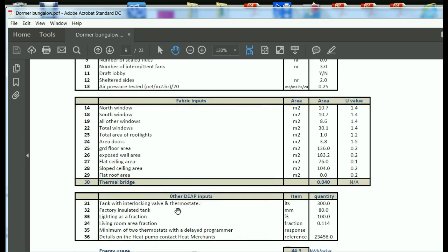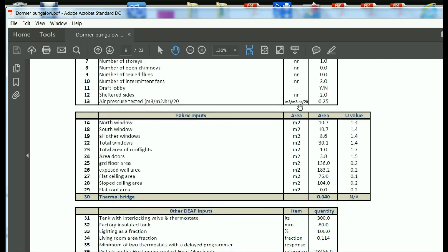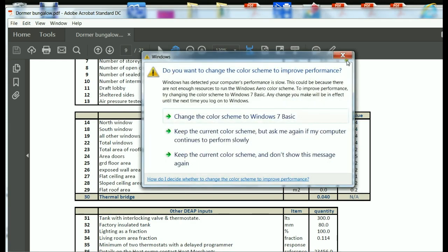It then runs the U values for the floor, wall and roof through the calculator until cost-effective compliance is achieved. It only uses the more expensive higher performance windows if necessary, but it never uses an air tightness less than 5 because of the more expensive heat recovery unit.